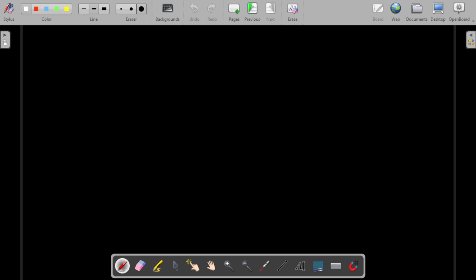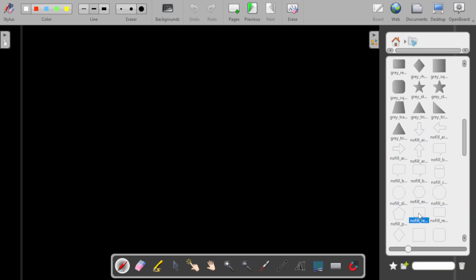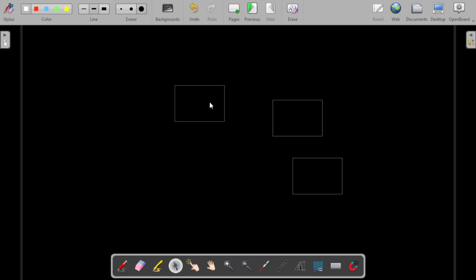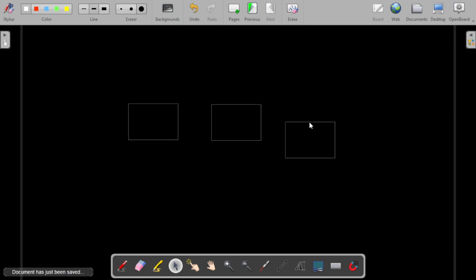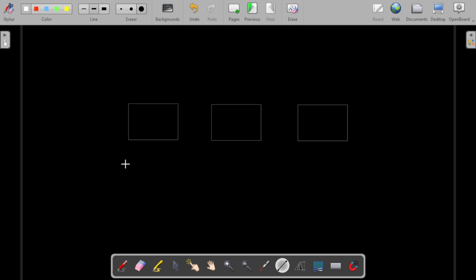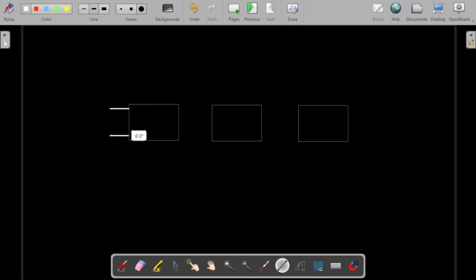So let us now design the circuit. So these are the 3 flip flops. I'm arranging them sequentially. Here we know J0 and K0 are 1, so let me connect them directly. Okay, so this output will be 1, and the clock is as it is. It is synchronous, so the clock will be applied to everything. So let me complete the clock connection for everyone.